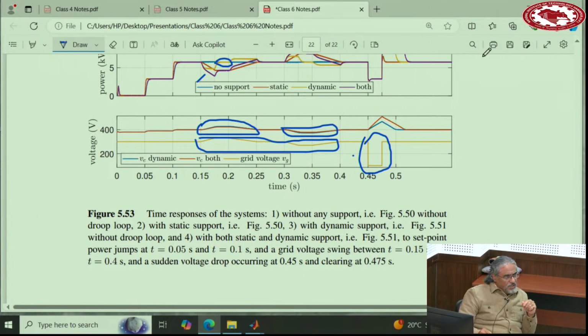So the only case that you need to use K3 is if you are pushing the system to the extremes. You are choosing very small R1, you are choosing gamma equals 0, you are choosing very small C, which means you don't care about inertia, and then you want to have very tight voltage across the capacitor. This is a very extreme case. In this case, as I explained here, you need to go through that full state feedback and use K3. But other than that, my experience is K3, don't use it. It makes complications in implementation.